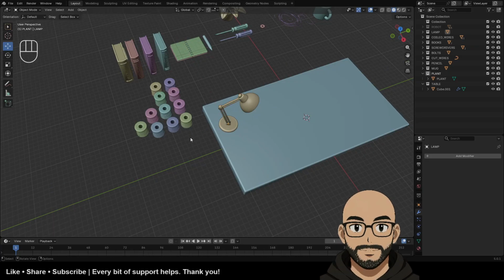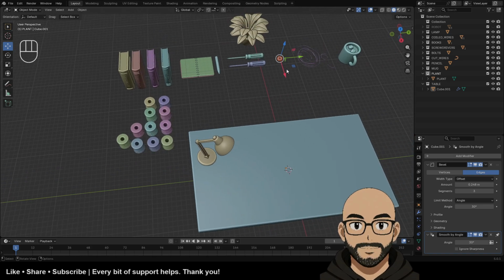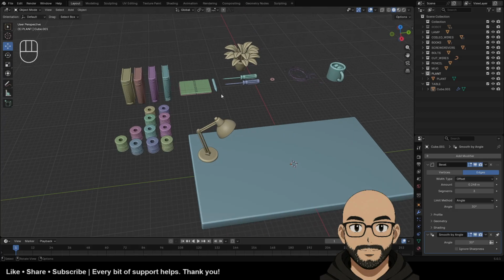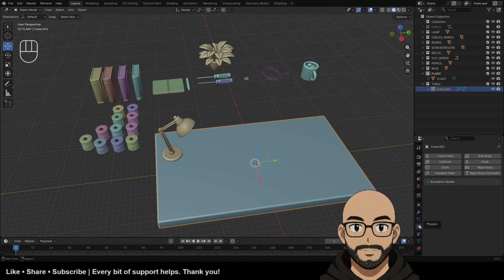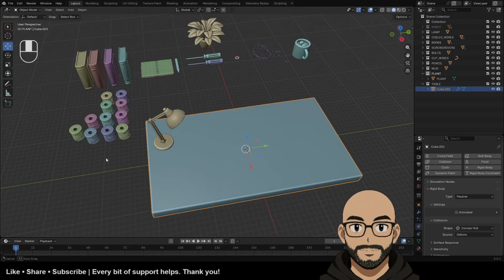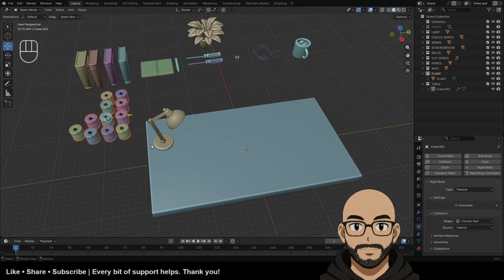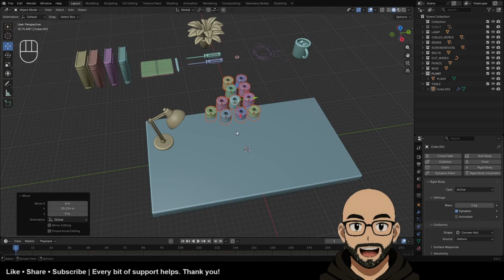Move it somewhere over here. Now, these objects I kind of want to place randomly. Same with these screws, right? So what I'm going to do is actually go to physics. I'm going to go here. It's going to be a rigid body, passive. Right? We don't want anything to go through that. Got all of these. We're going to say this is a rigid body. So they're all rigid bodies and they're active, right? And we're going to move these up.